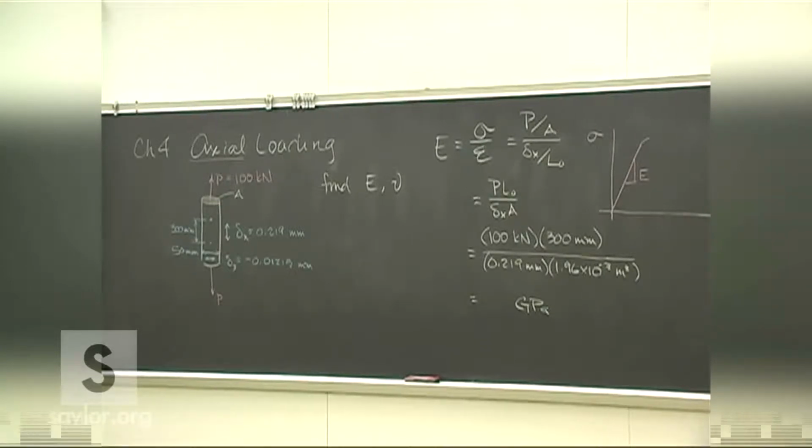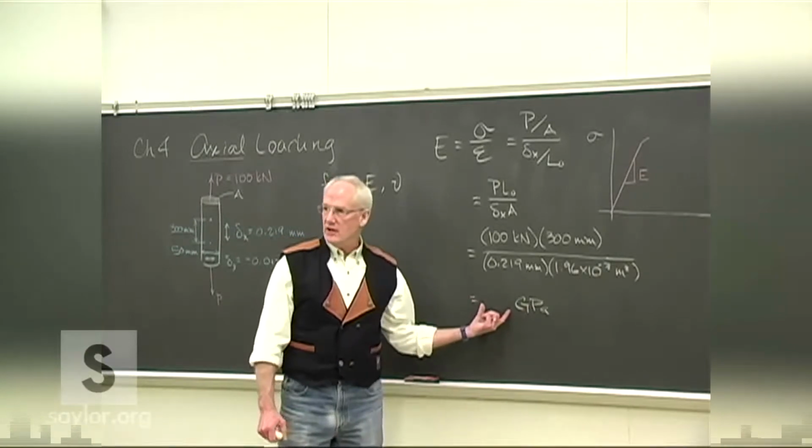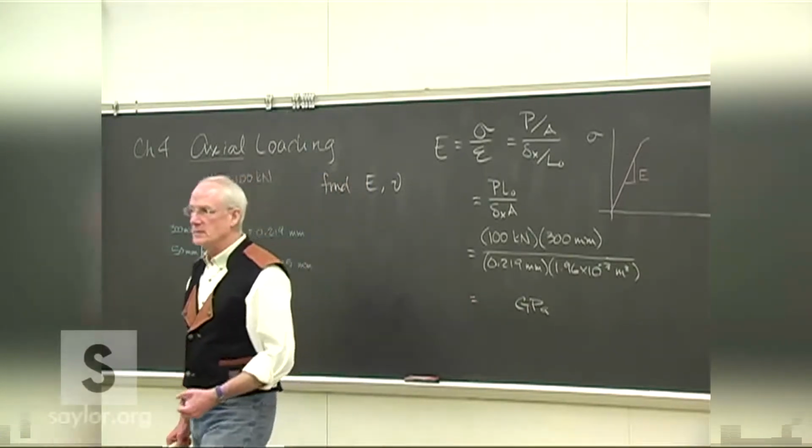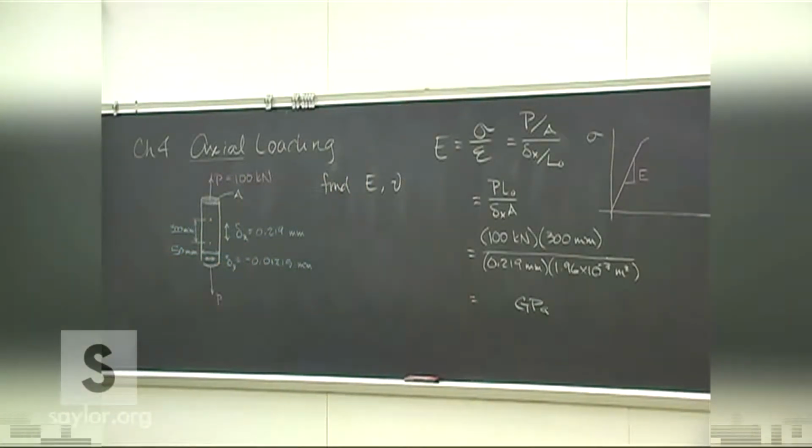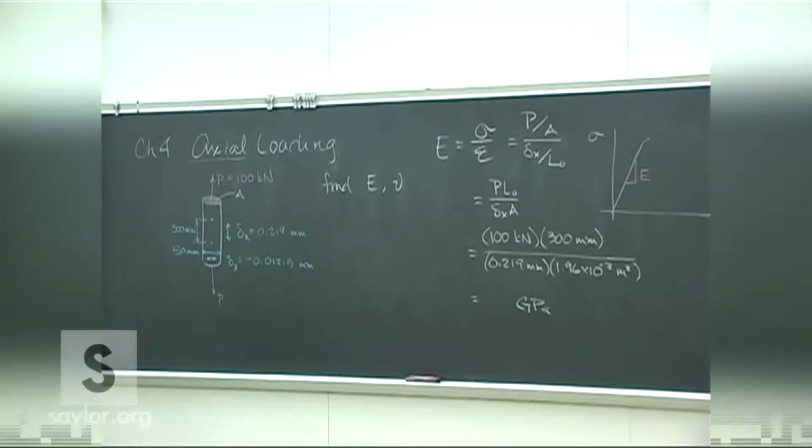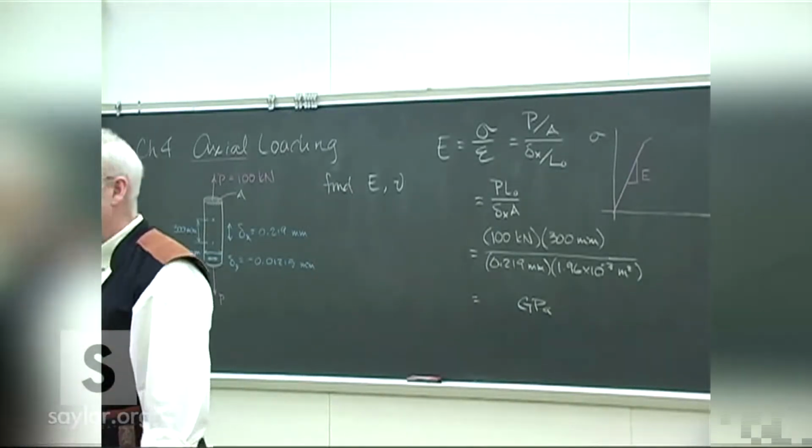A little bit of roundup. It's not of great concern that we have a lot of precision on these numbers. Remember, we're going to build in a big factor of safety depending upon the application and what could happen in the case of failure, but the factors of safety are typically from 1.5 up to 5, 6, 7 even. Depends upon what would happen if we had catastrophic failure.